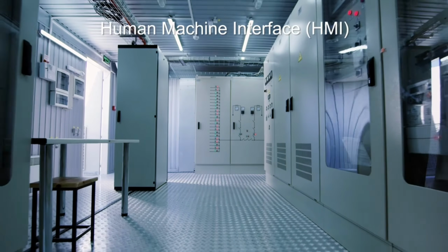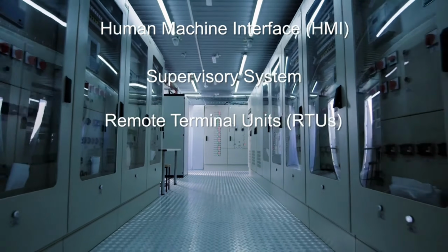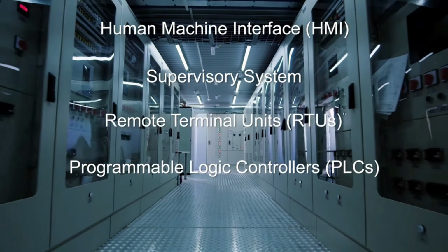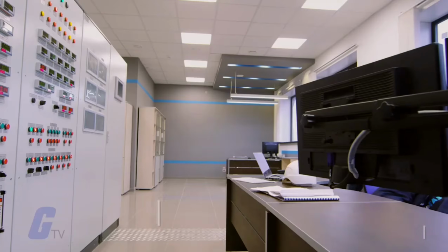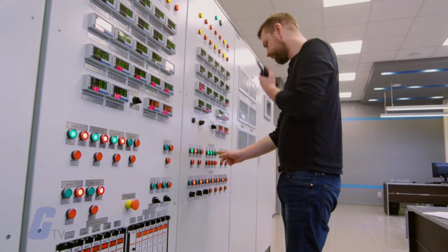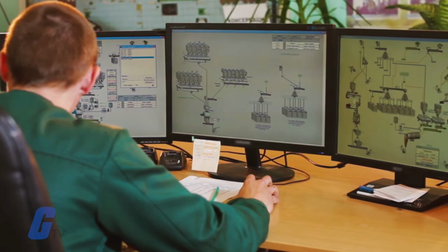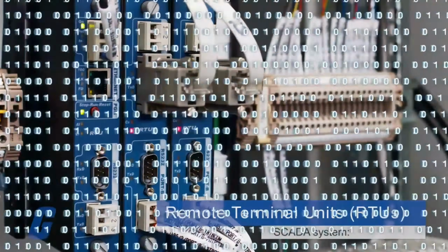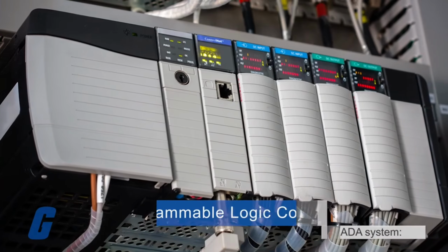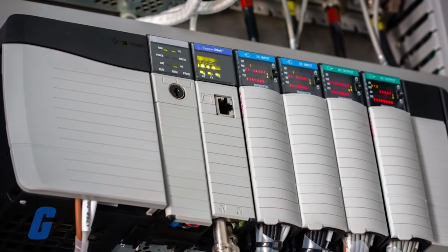There are 5 essential composing parts of a SCADA system: human-machine interface, or HMI, supervisory system, remote terminal units, or RTUs, programmable logic controllers, or PLCs, and communication infrastructure. The HMI processes data and sends it to a human operator, where they can monitor or control the system. The supervisory system gathers the data and sends commands or operations to the process. The RTUs connect sensors and convert their signals to digital data and send it to the supervisory system, where it can be stored in a distributed database. PLCs are used as field devices because they are much more versatile and economical than process-specific RTUs.